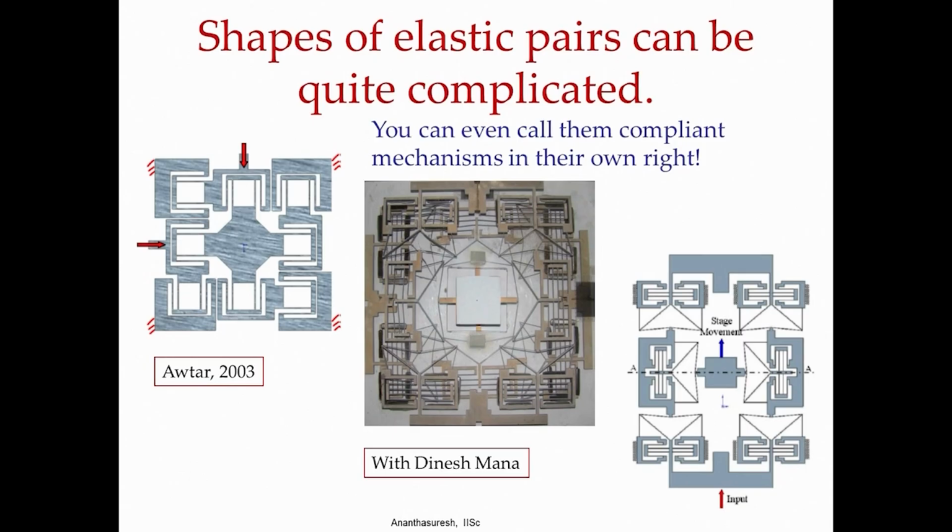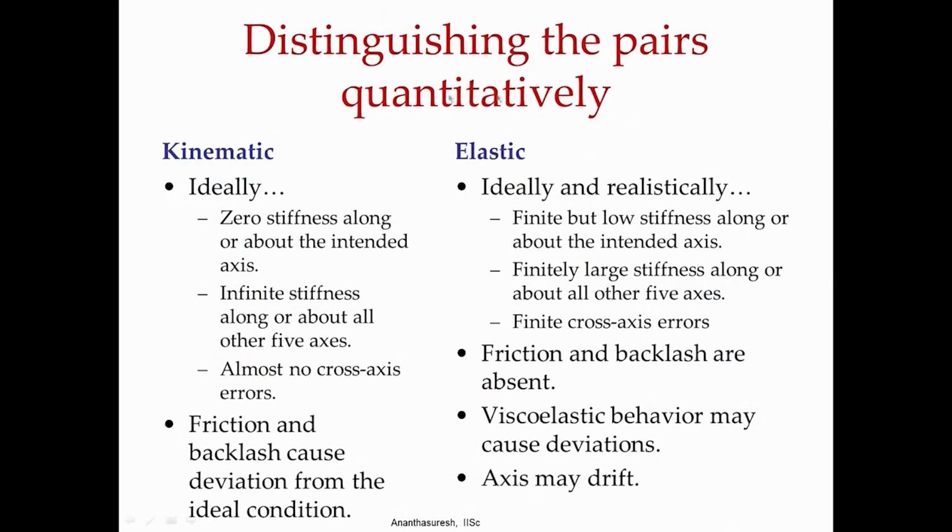This again I emphasize the difference between kinematic pairs and elastic pairs. If you compare these two, that is distinguishing kinematic pairs and elastic pairs, you have in a kinematic pair ideally, meaning that there is no friction or backlash, 0 stiffness along or about the intended axis.